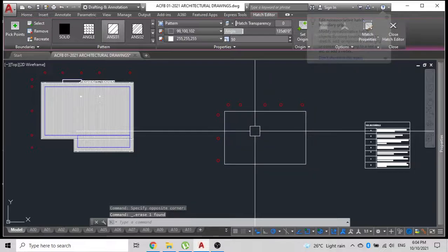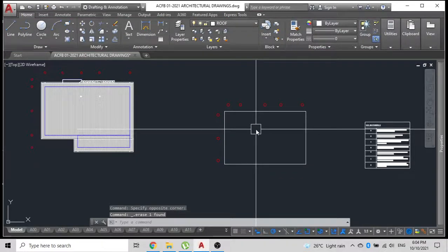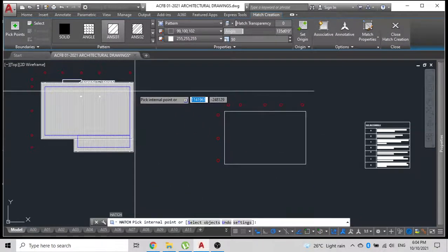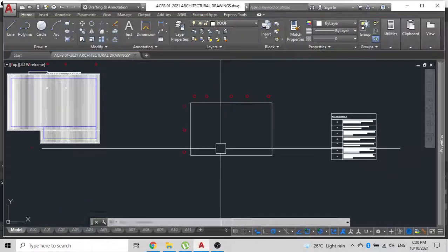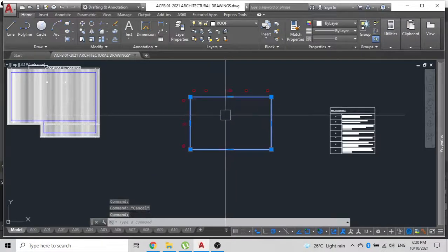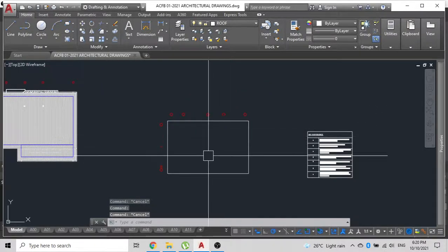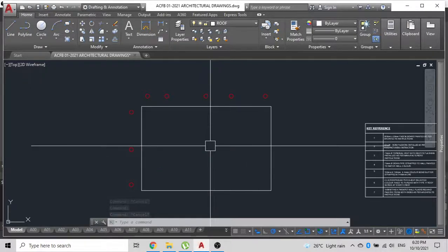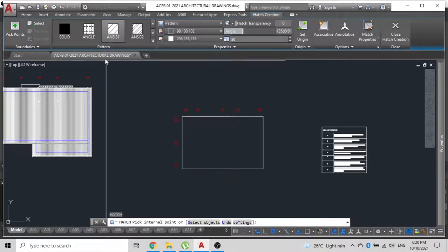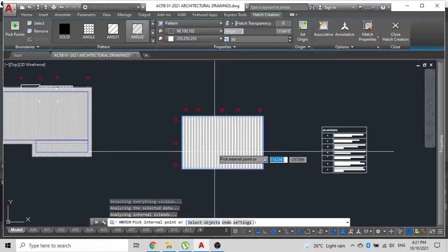Now the other thing you can do is simply create your own hatch, which is simply by typing H for hatch, then press enter. So after turning off the layer for the unnecessary items, what you will need to do is set up your hatch. Now I've already shown hatch in option number 1. Let me show you how to do another hatch. Now this is a longer process. So what you do is you type H for hatch, press enter, then select the hatch, this hatch over here, ANSI32. Don't worry about the angle now, and click it in there.